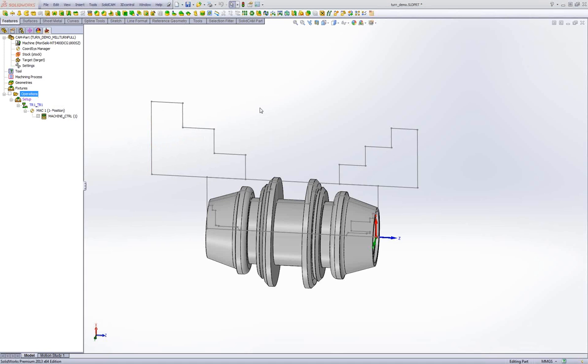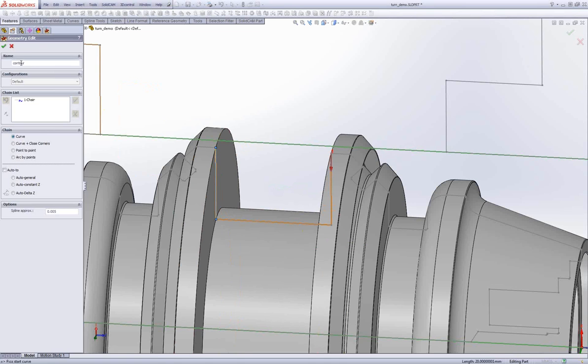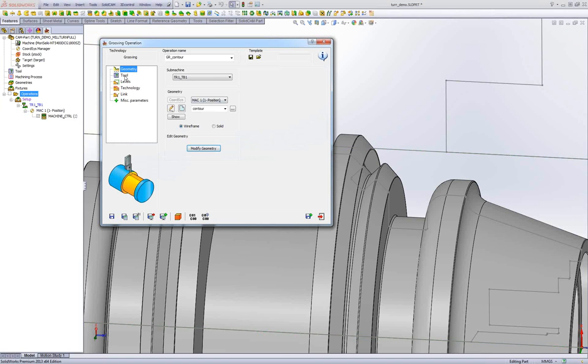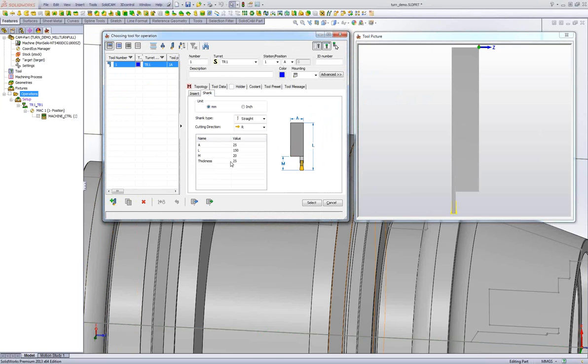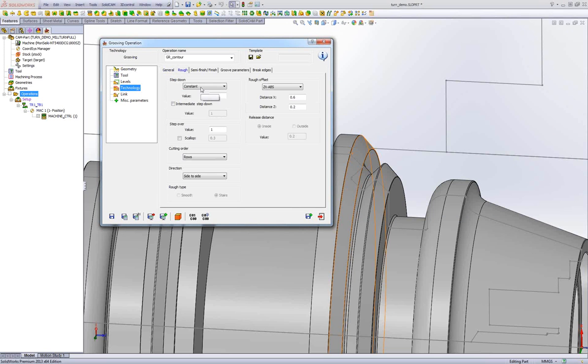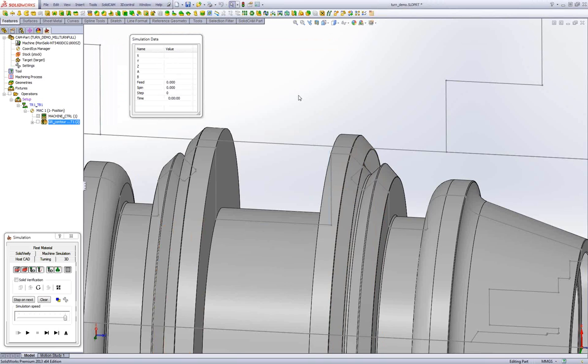Add a grooving. And modify the geometry. Extend. We select a tool, a standard tool for now. Just shrunk, let's make it a little bit bigger, 30 millimeters. Select levels, technology, long external, rough, single, from middle outside, smooth, distance, without finish, you don't need finish. Simulate. Let's see where the tool path is starting.